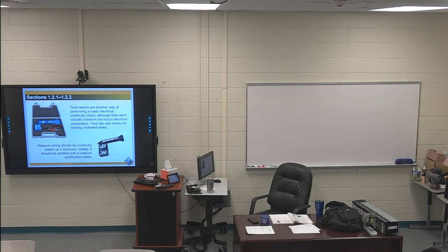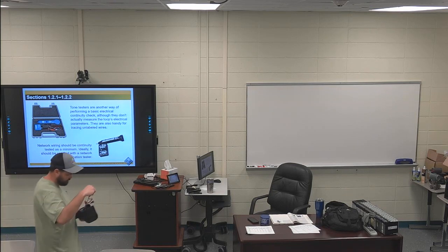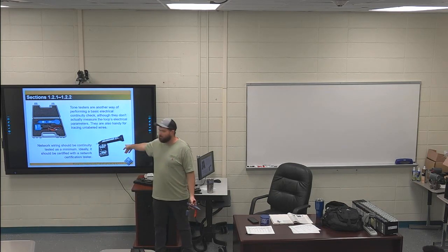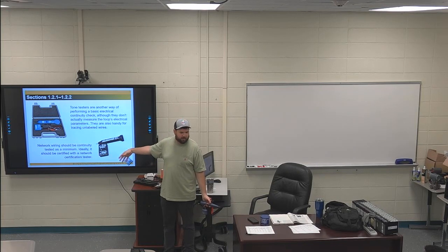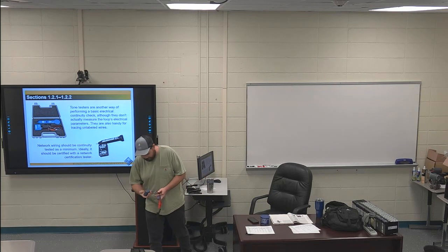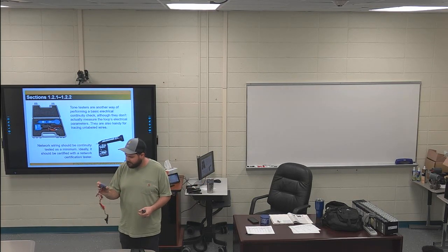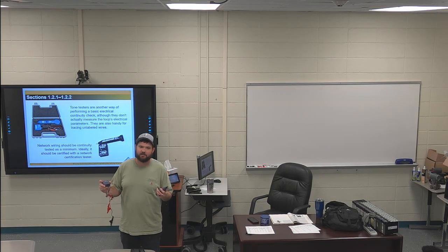So the technical name is a toner, but at least at the steel mill I worked at, a lot of them called it a Fox and the Hound, which is a name brand. It's like saying Kleenex for a tissue. But you can check continuity and stuff like that. I don't necessarily use it for continuity.